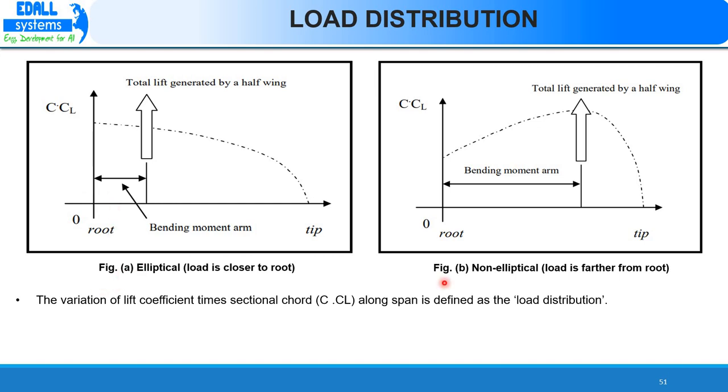If the load is far from the root, the bending moment is more at the wing root and the load distribution is non-elliptical, as shown in figure B. Load distribution is a function of lift distribution. The major application of load distribution is in wing structural design.